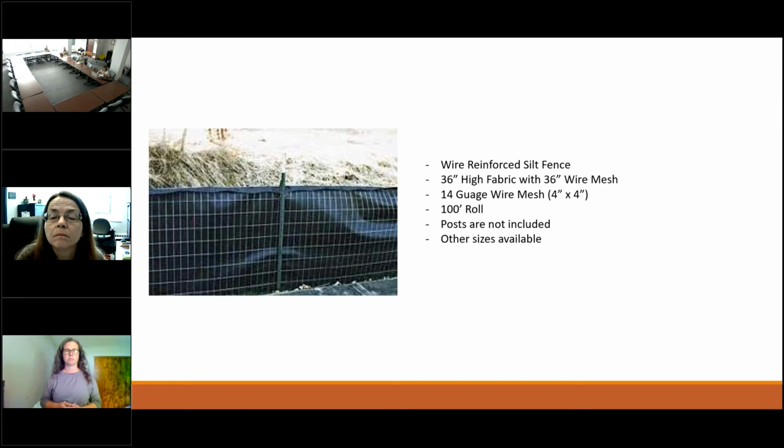And so again, with the silt fence, the key with that is it must be inspected and maintained. I know often that'll be part of a SWPPP plan where that will need to be maintained weekly or monthly. The installation on silt fence is somewhat cumbersome. You know, the bottom 6 inches is typically trenched in place, which means that you are creating yet more soil disturbance on site, which is, I'm sure, especially not as desirable when you are along a creek or a ditch bank.